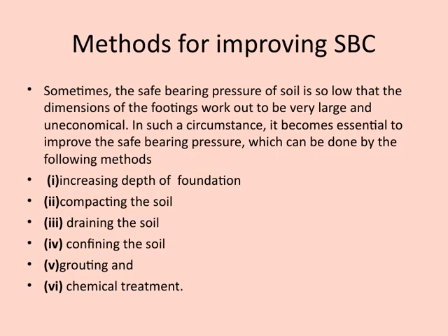When the safe bearing pressure of soil is quite low, it often results in the need for very large and uneconomical footings. This is where improving that safe bearing pressure becomes really important. By doing so, we can design more practical and cost-effective foundations. One method is increasing the depth of the foundation, which allows us to reach firmer soil layers that can bear more load. Another approach is compacting the soil, which improves its density and strength.